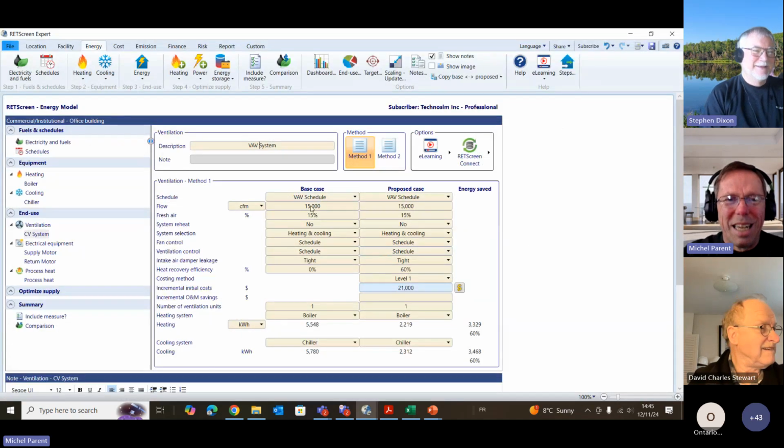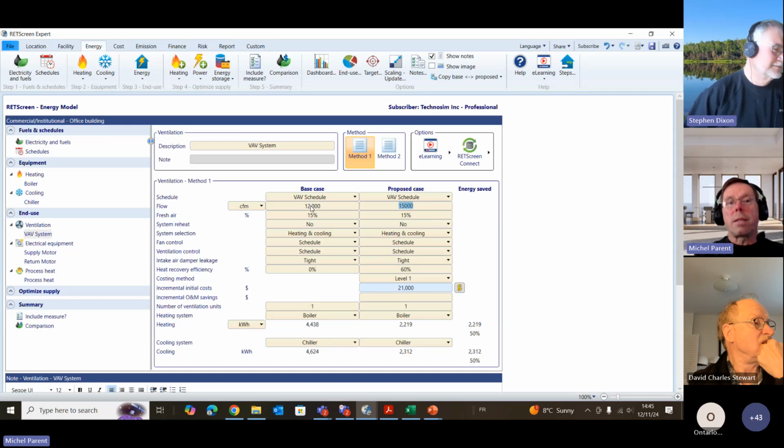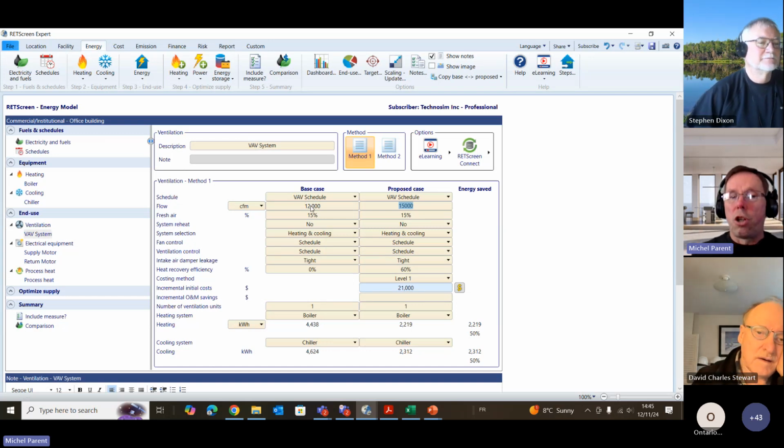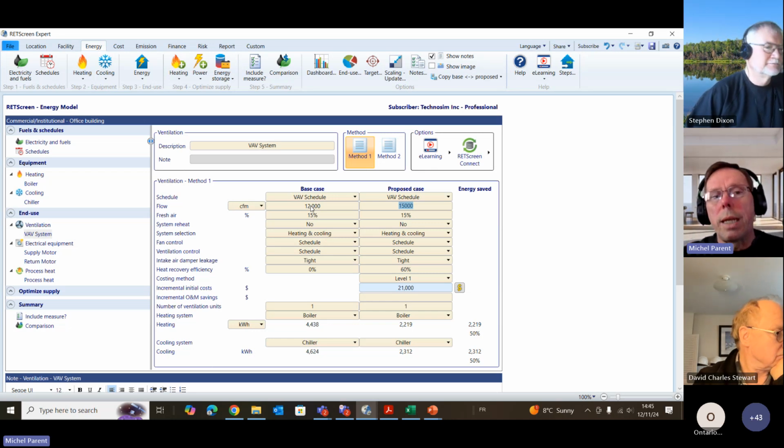So we enter 12,000. We can both agree and be wrong. Yeah. So 12,000. So that's an easy mistake. Don't forget, a VAV system should not be running at 100%. Maybe they are. And if they are, that's a bad thing, but they should not. So you would enter the average flow.